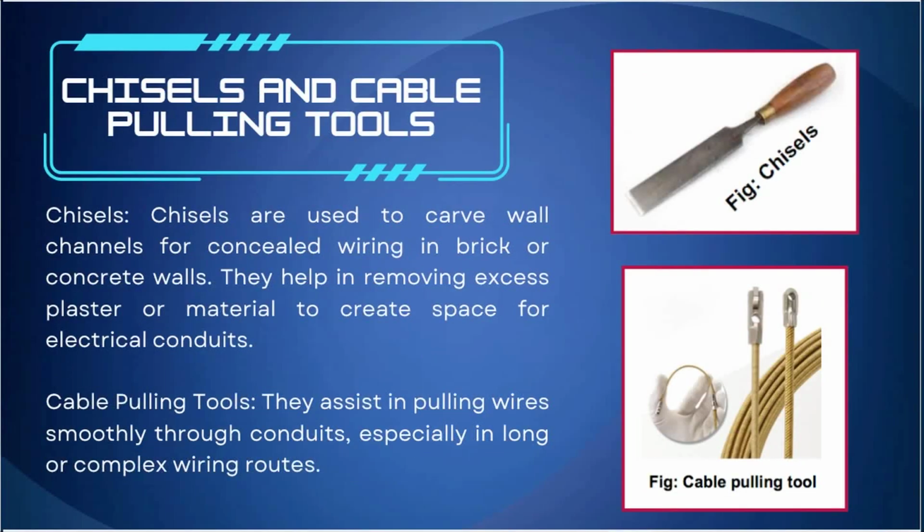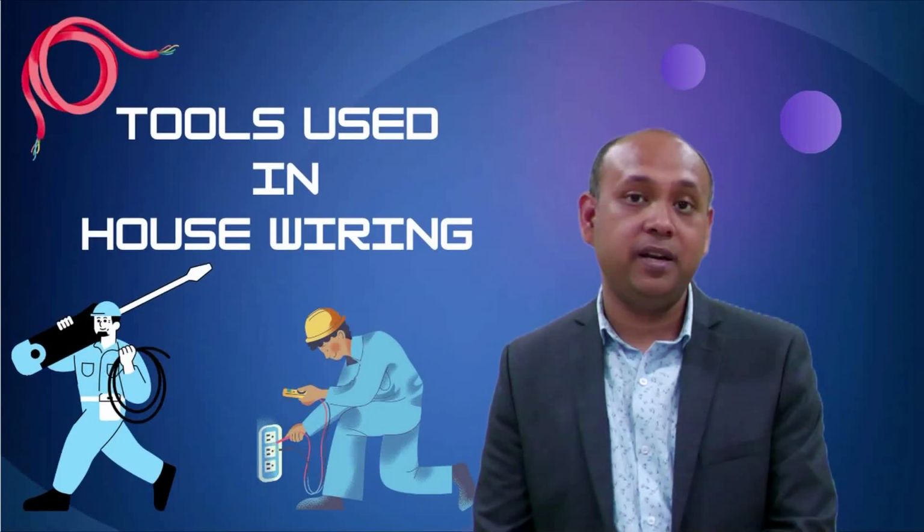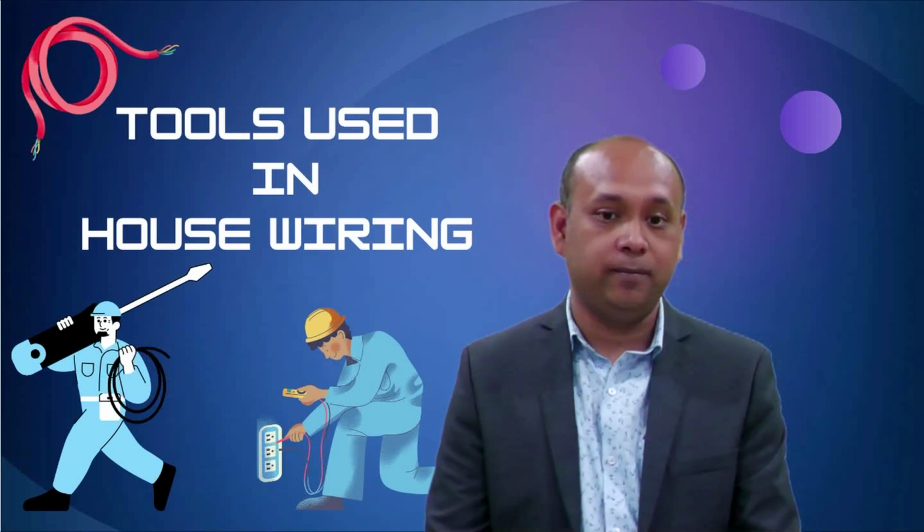Chisels are used to carve wall channels for concealed wiring in brick or concrete walls. They help in removing excess plaster or material to create space for electrical conduits. Next is the cable pulling tools. They assist in pulling wires smoothly through conduits, especially in long or complex wiring routes. This completes our discussion on some of the important hand tools essential for house wiring.